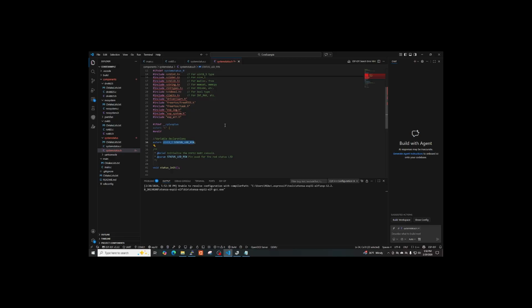Is the non-volatile storage system operating properly? Is it faulting out? Is the temperature sensor overheating? Do we have a general fault from the stepper interface? Those are the kind of faults we want to at least have access to. So if there is a problem with the board, we can at least see a general idea where to look to troubleshoot it.